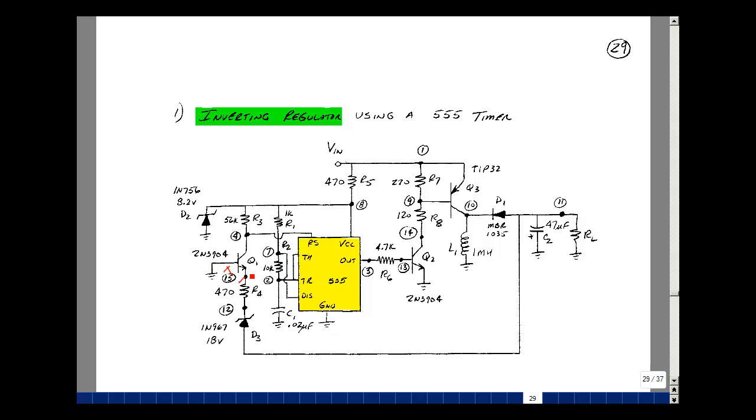is around 0.6 volts. If current were to flow this way, then let's find the node voltage here. It's going to be equal to minus the Zener voltage, minus the drop across the resistor, minus 0.6. And this is an 18 volt Zener. When this node voltage gets to be minus 18.6, current's going to be flowing in this direction, back through here, and that's going to cause this transistor to saturate, pull the reset pin low, and it's going to set the output low.